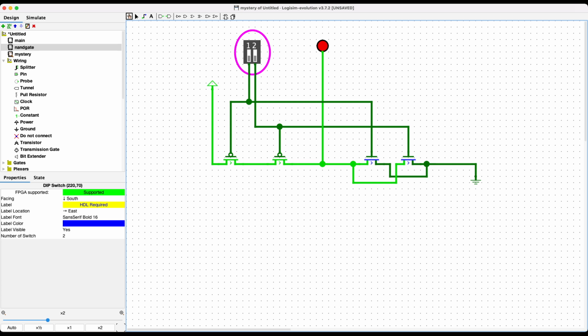Well, what about if I want a regular OR gate? With a, yeah, an inverter or a NOT gate, okay? So in the same way that I had a NAND gate and I had a NOT gate, and I could put those together to make a regular AND gate, could I take a NOR gate and a NOT gate and make it a regular OR gate? Yeah, Cole, you look befuddled.